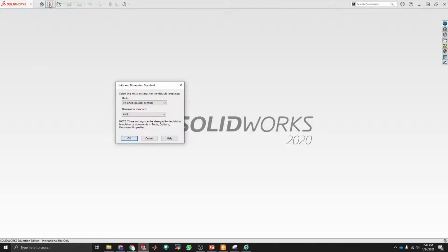So I'm going to click here on the blank paper. That's for creating a new part or a new document. And immediately it is asking me the dimensions that I'm going to use. In this class, we're going to use millimeters, grams, and seconds. And then I'm going to click OK.